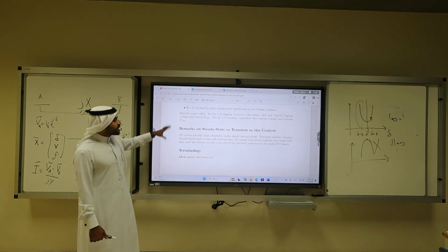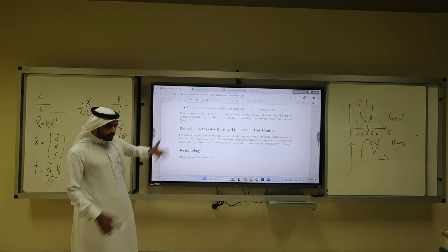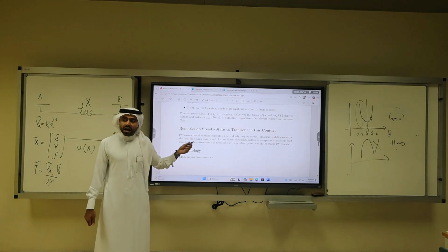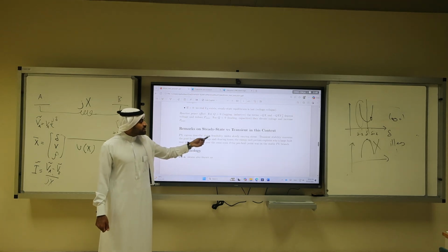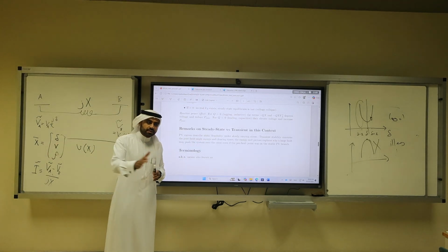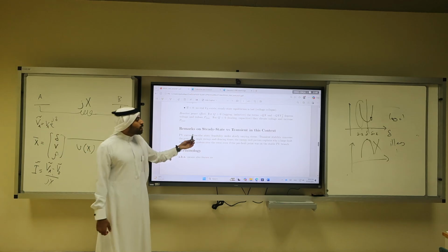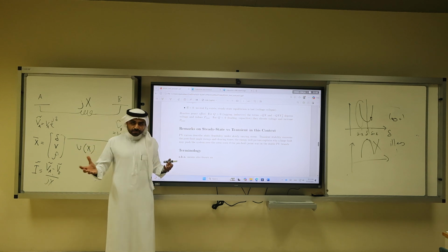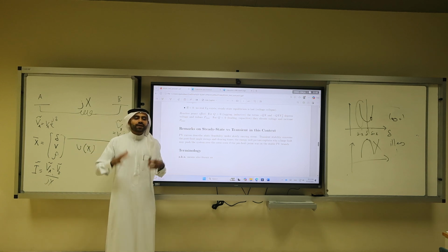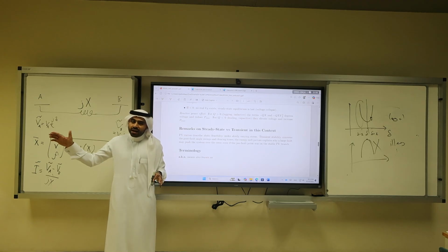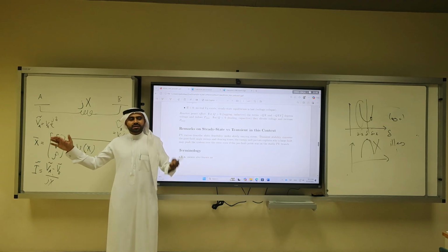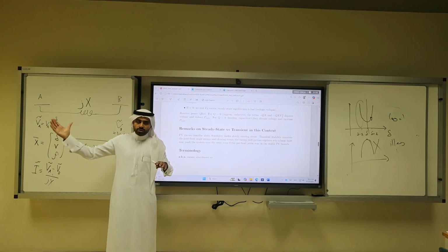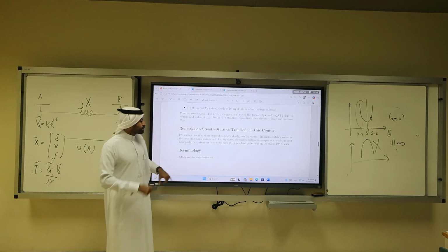So what are the remarks on steady state and transient? What do we understand from steady state and transient? PV curves, which we're going to have a lot, describe the static feasibility under slowly varying stress. If you change the operation slowly, how do those PV curves look? Transient stability looks at the big events, a big fault in the system. This is 522. In this course, we're going to have a load disconnected, a line disconnected, small events that are gradual. So the automatic voltage control is slowly moving.